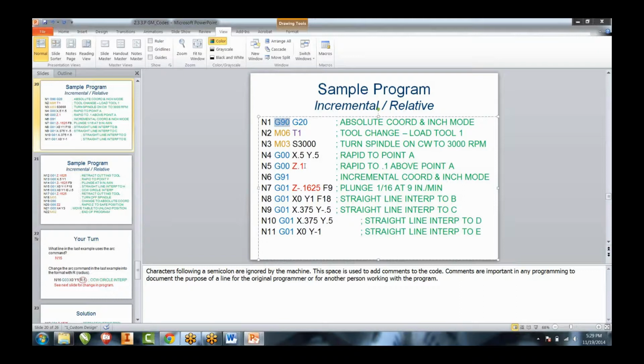As soon as you get to point A, you're up 0.25 above point A, then you enter incremental mode and go incremental from there. Otherwise, it gets really ugly because you have no idea where the XYZ value of the tool change is. So that makes it a little easier for kids to understand too. Just don't forget that when you do your relative for the first time.